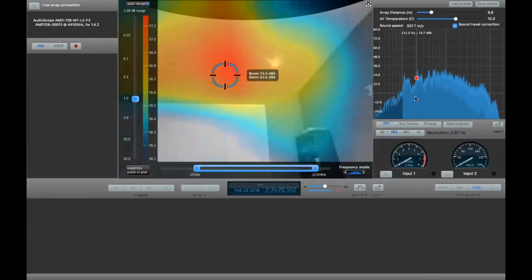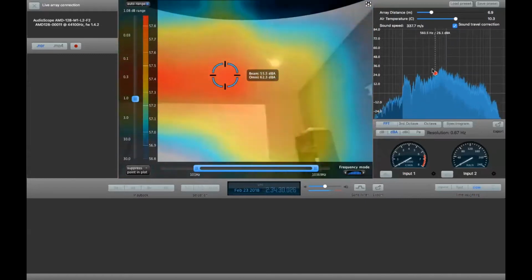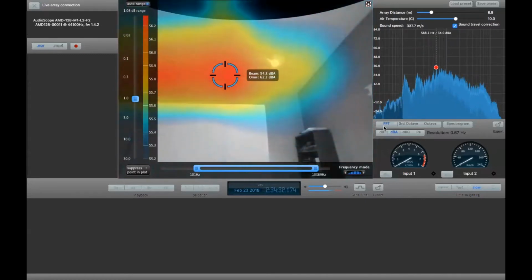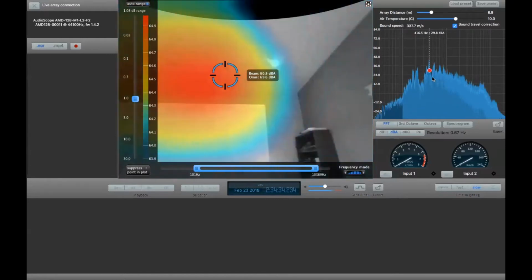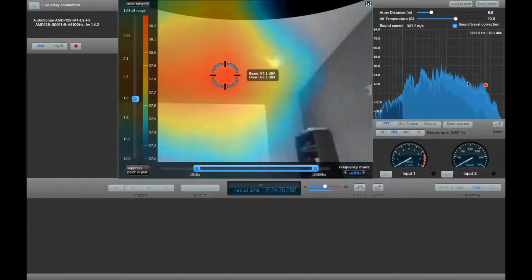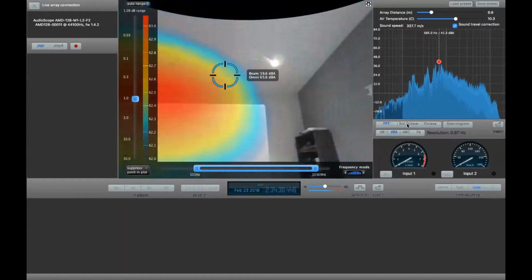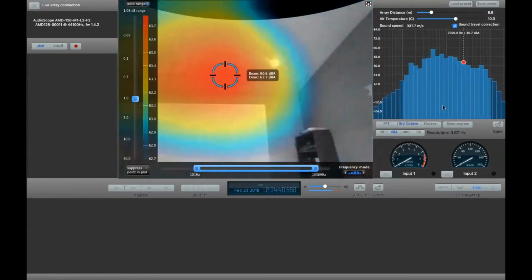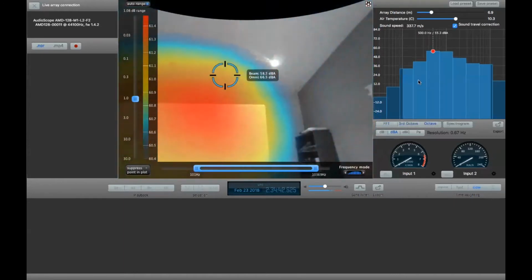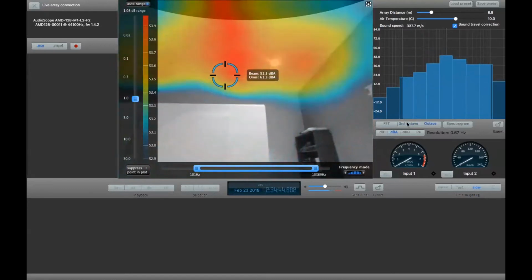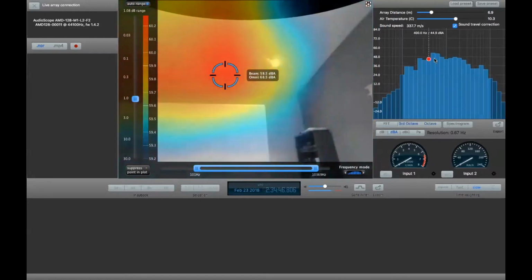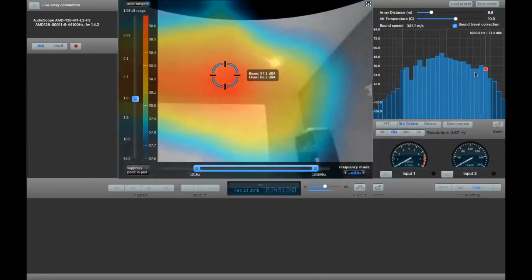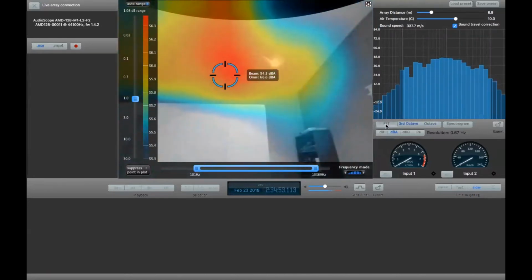It's just a nice telephone, so it's not the highest quality loudspeaker. FFT is a fast Fourier transform that gives you the spectrum of the noise. You can also do third octave bands and full octave bands. A lot of times I like third octave bands because it makes it a manageable amount of data if you're comparing different things.